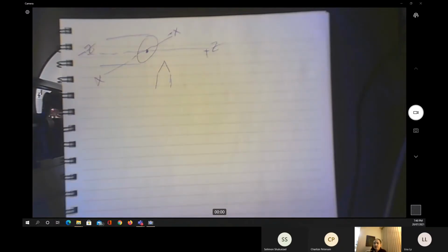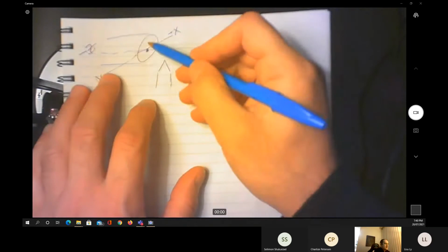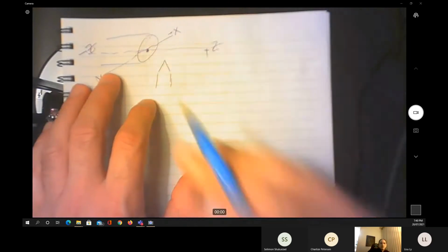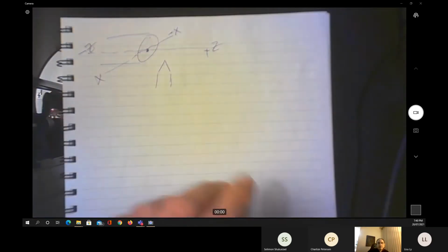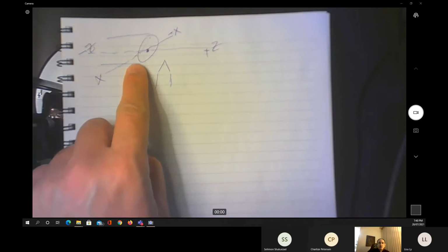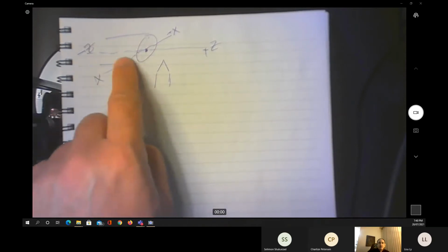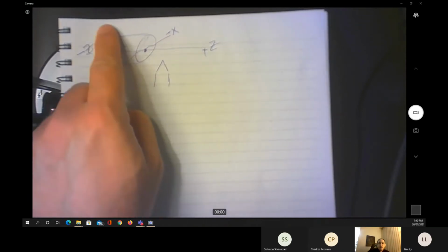You remember that we have different cuts on the turning operation. The first operation is we can do the face cutting, just remove a layer from the face. Then we can do the actual turning by removing multiple layers. We can have the contour cuttings by making the curves.